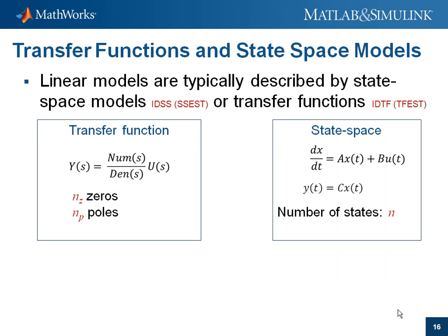Linear parametric models can be written as input-output transfer functions, where the input relates directly to the output in a difference or differential equation. These equations are often written in terms of Laplace or Z transforms. They can also be written in state space form, using a state vector as an intermediate variable. The flexibility or size of a structure is described by one or a few integers: the number of states n, or the number of terms in the numerator and denominator of a transfer function, that is the number of zeros and poles, nz and np.